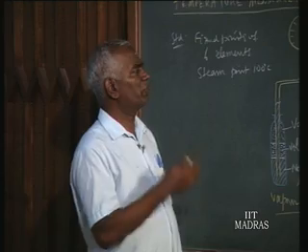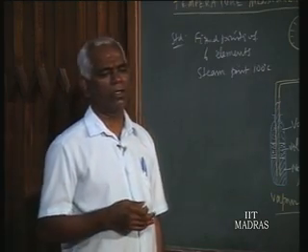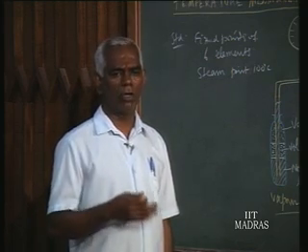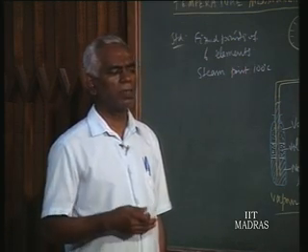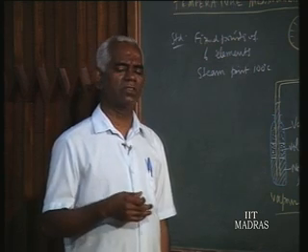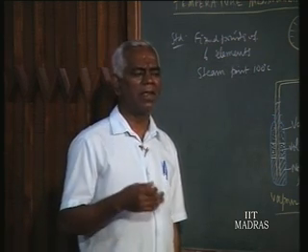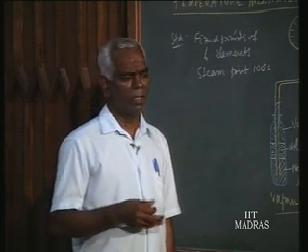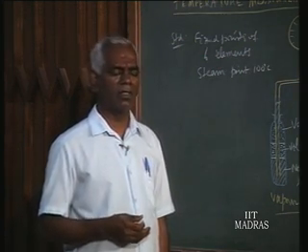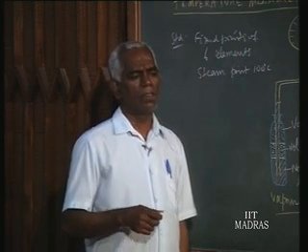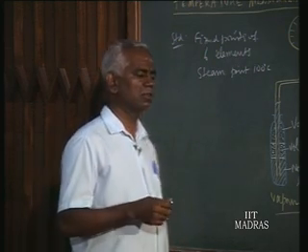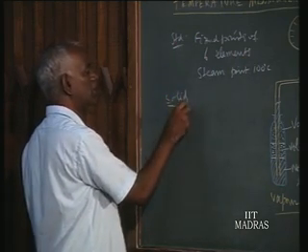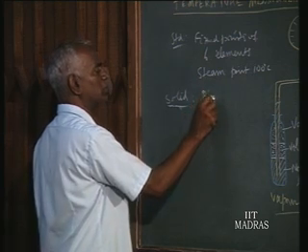Now, for the purpose of measurement of temperature, we use the effect of temperature on bodies. It changes the physical dimensions or volume of the body, and electrical properties of bodies or elements are changed when temperature is changed, and the radiating capability of a body or matter is again a function of temperature. By using these properties of matter, we are able to measure temperature. First and foremost, say solid. Expansion of solid we are using in the form of bimetal strips.